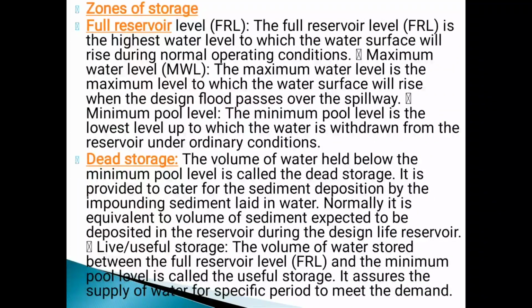Next, zones of storage. Full reservoir level, FRL. The full reservoir level is the highest water level to which the water surface will rise during normal operating conditions. Next one, maximum water level, MWL. The maximum water level is the maximum level to which the water surface will rise when the design flood passes over the spillway. Next one, minimum pool level. The minimum pool level is the lowest level up to which the water is withdrawn from the reservoir under ordinary conditions.